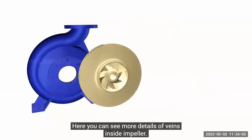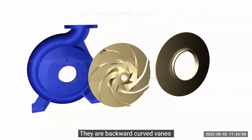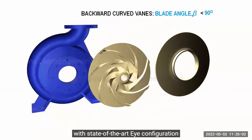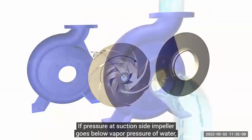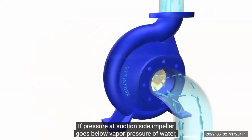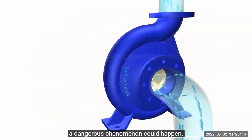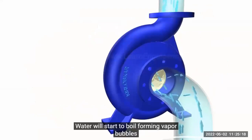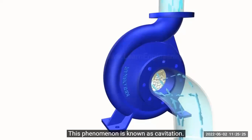Here you can see more details of vanes inside impeller. They are backward curved vanes with state-of-the-art eye configuration. This vane is extracted from a Kirloskar pump model. If pressure at suction side of impeller goes below vapor pressure of water, a dangerous phenomenon could happen. Water will start to boil, forming vapor bubbles and spoil impeller materials over time. This phenomenon is known as cavitation.